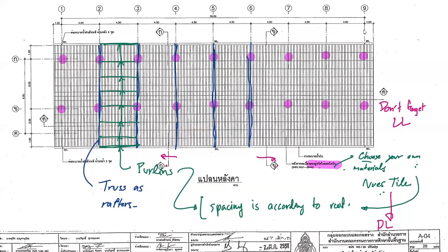You know, there's one thing that used to be so popular for the roof tile. It's called CPAC Monier. It's a very, very heavy material, and it requires some kind of special framing system for the installation. And in the end, by the dead load itself, it could be something like 50 kilograms per square meter.